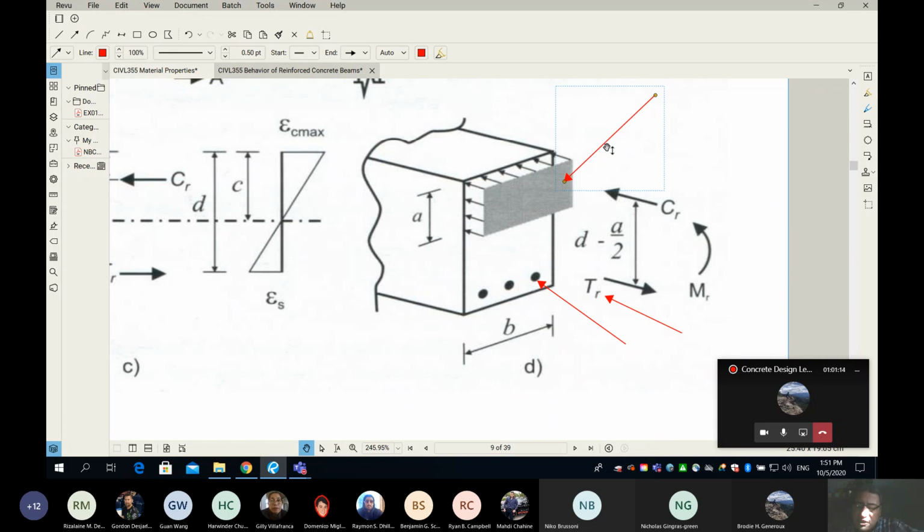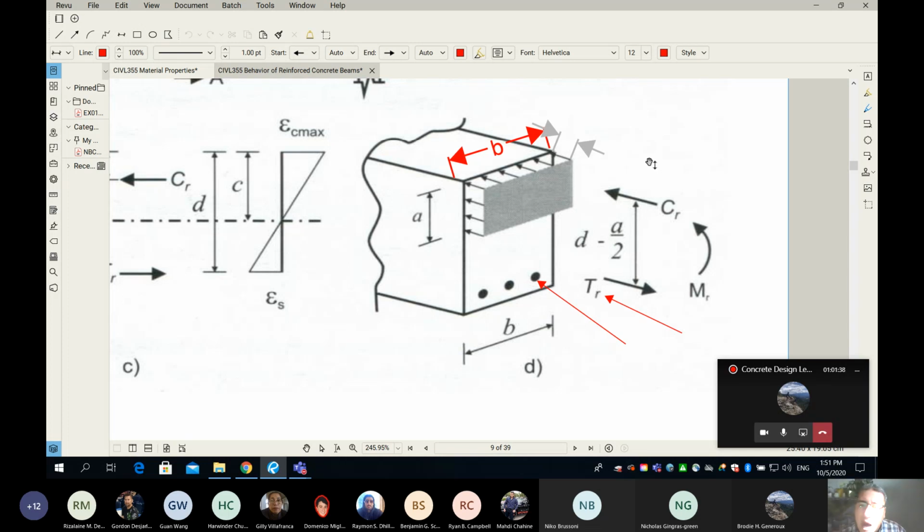Okay? Probably, guys, you need some dimensions. I'm going to show it to you one more time. So the width is here, from this point to this point, and this is the width of the beam. It's called b. And then finally, the stress is from this point to this point here, so this number is equal to alpha 1 phi c f prime c. Are you following?